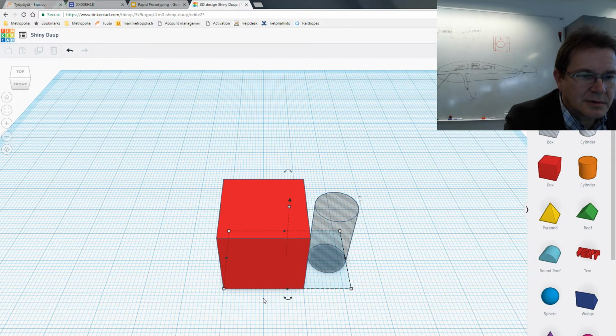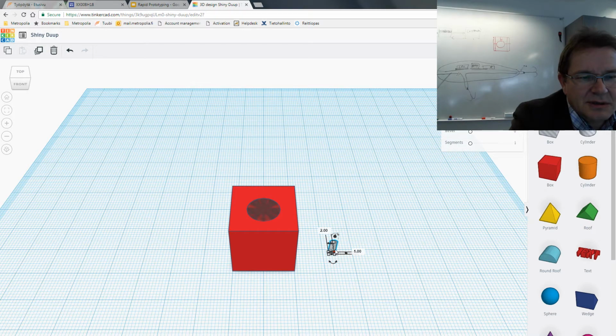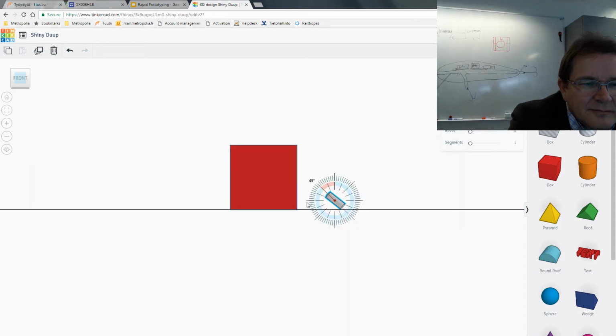Maybe I should have. It should actually be a total hole. But anyways, then I need to basically make a hole here. So what I can do, just make another cylinder. Take another cylinder. Make it a smaller one. Maybe say 7, 6. Oh, that's just tiny. 6 millimeters, and then make it 2 millimeter wide, and then I can rotate it. Let's rotate it the correct way. Rotate it. There's 90 degrees. Okay. Rotate it, and then